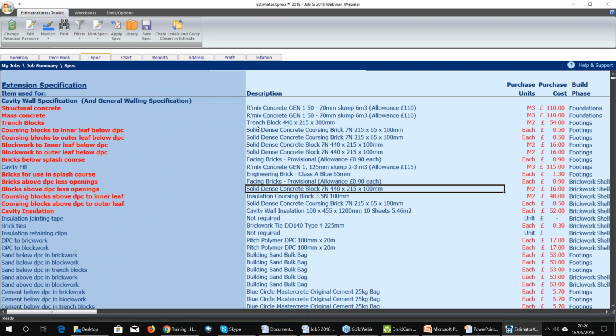Usage factor is important there, how the blocks are purchased. If the blocks are purchased individually, like say a Travis block or something like that, then you'd want to make sure that's 10 per meter square. If it's a Jewson block, then that would be purchased per meter square. It's one of the times that the material ordering is different on the same material type across different merchants. We've traditionally gone with the meter square ordering system, but it's just a case of times by 10.